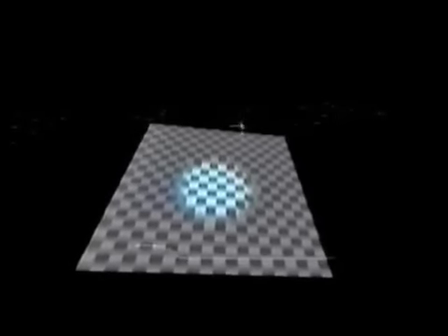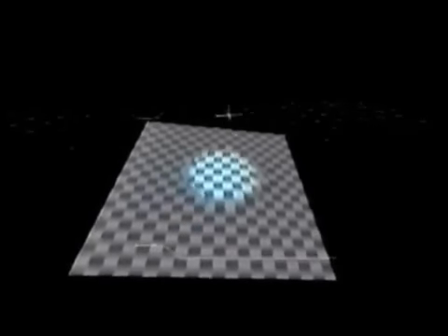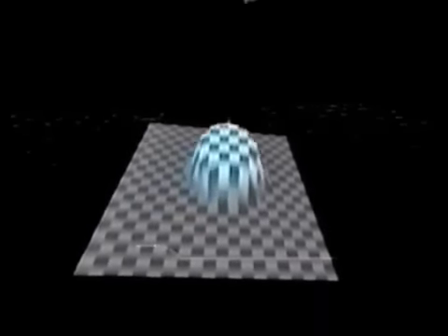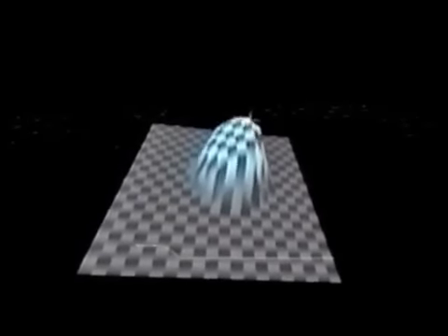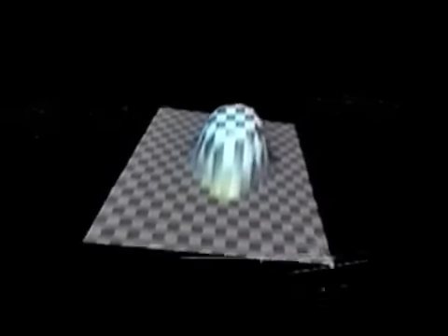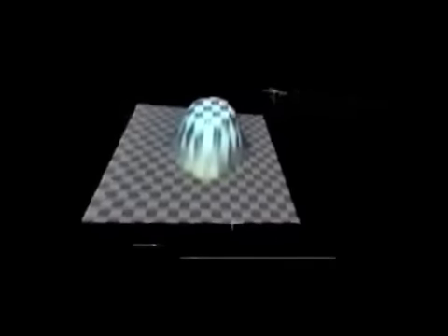Some experiments in shaping of surfaces in virtual reality via direct manipulation of the surface. This particular paradigm uses a point-like grab of the surface, where you grab the surface like so and lift it up, and then the area of influence of that move are controlled by various mathematical functions, which are analogous to Alan Barr's spatially weighted transformations.